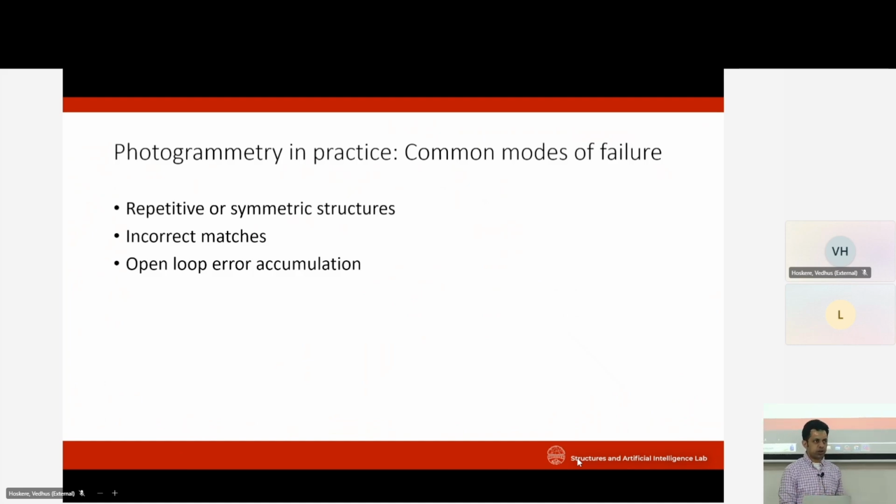If you don't close the loop when you're doing a photogrammetric scan, then it's difficult to ensure that the bundle adjustment, where you optimize for the cameras, poses, and points, results in accurate geometry, because the optimization process can lead to drifting, and the way to correct for that drifting is to have a closed loop. So that's why it's important.